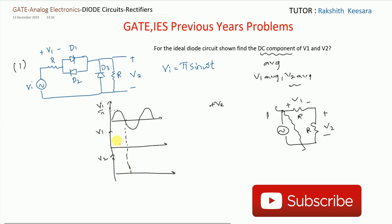So during the positive half cycle, it is divided equally. So you will get pi by 2 here and pi by 2 here. During the negative cycle, what will happen? Negative is connected here. So diode D1 will be in reverse bias, off state. Diode D2 is forward biased and diode D3 is also forward biased.